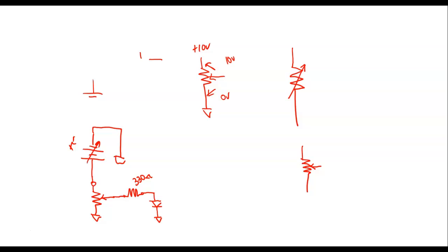And the transformer is even isolated from that common. So when you're doing your power supplies, the common is your common. It has nothing to do with that common on there. And that's what happens when people do this lab, is they'll hook up their common over there to the common on the trainer, and then all their measurements are wrong.